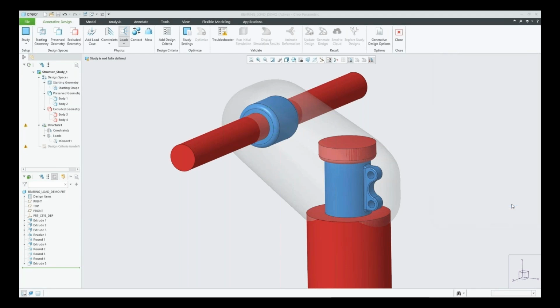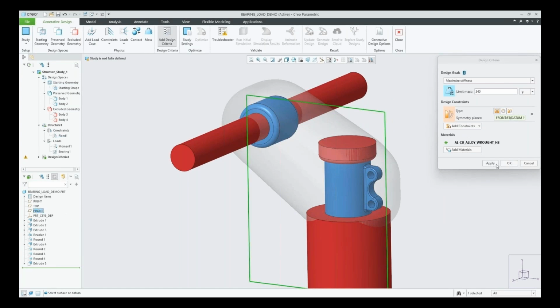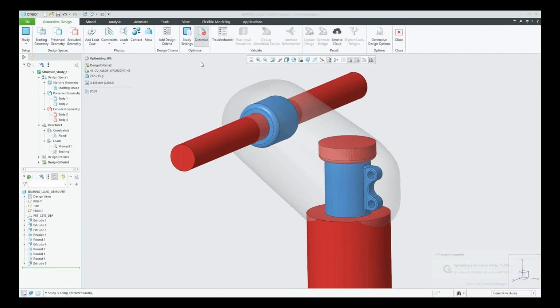So we're adding that cylindrical force in there as well. Some constraints where the other loads are or the position is, and depending on that, we add some design criteria. Of course, some limitations, but also symmetry. So the part must be symmetrical over a datum plane, and that's what it has to solve and try to optimize.